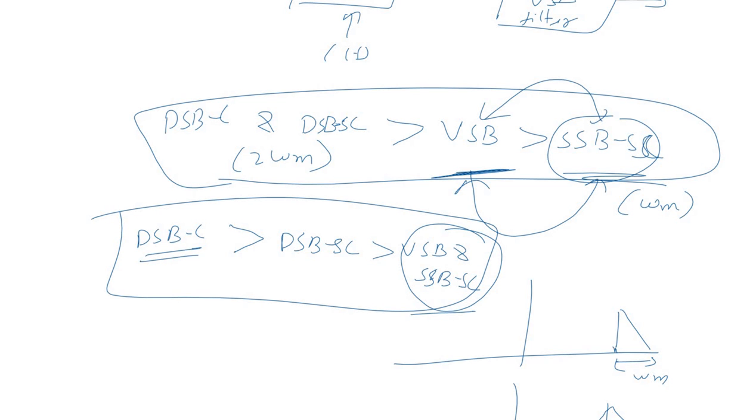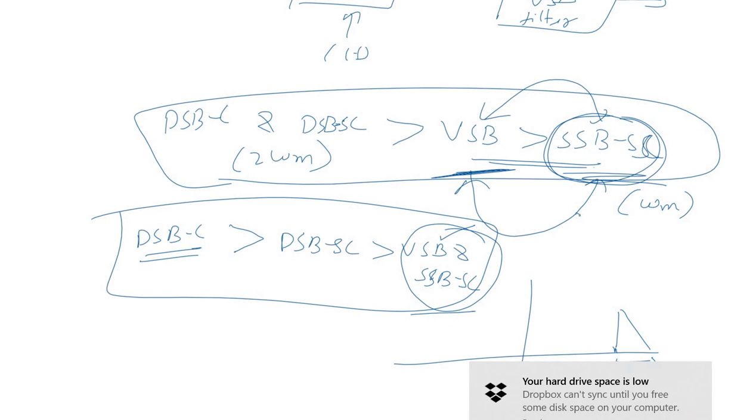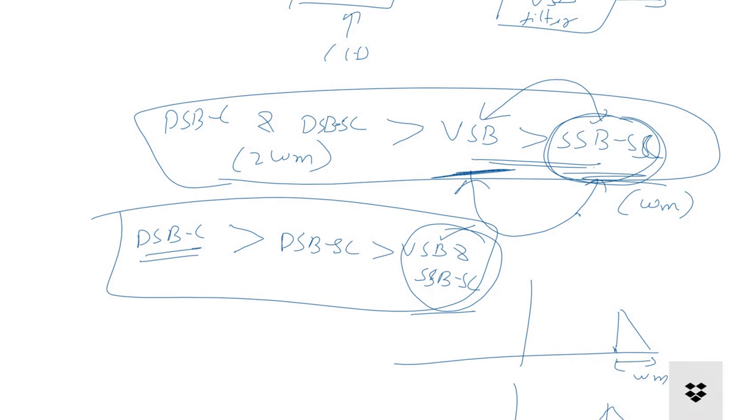Alright, so clearly we can see that in terms of power efficiency, VSB is performing quite well. In terms of bandwidth efficiency also, it is quite comparable, and it overcomes the issues of SSB-SC as well. So we can say that VSB is a very efficient technique.